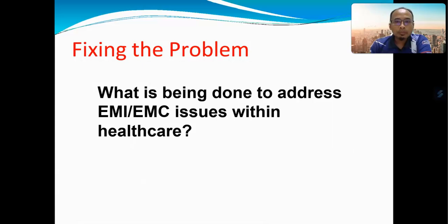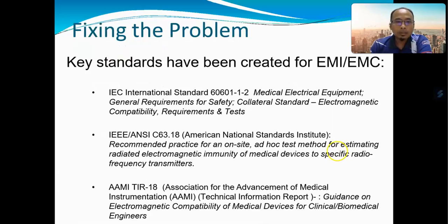So how to fix the problem? What is being done to address EMC and also EMI issues within healthcare? Basically, there are a few key standards that have been created for EMI and also EMC. For example, we have IEC International Standard 60601-1-2, which is for medical electrical equipment, general requirements for safety, collateral standard, electromagnetic compatibility requirements and tests.